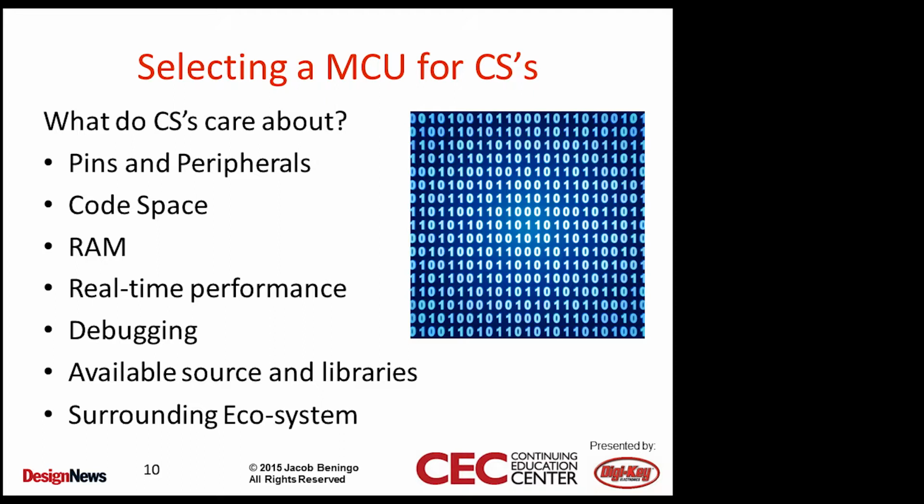Now, of course, with some modern microcontrollers, we don't necessarily need extra pins anymore. There are some cool debugging options available to us, which we talked about in the last Digi-Key Continuing Education Center session I did. But if you're using an old 8-bit microcontroller, one way is to use a couple of extra pins to do some performance measurements. One of the other things we're going to care about is code space.